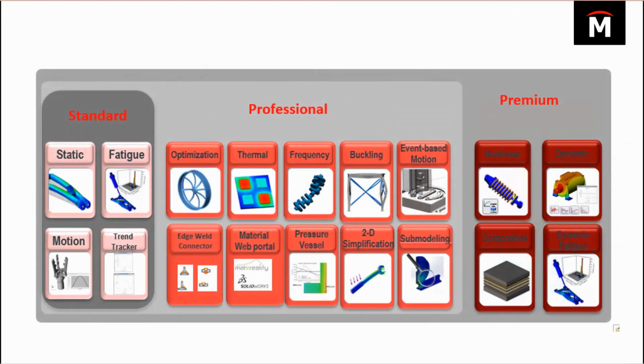I want to mention just quickly the 3 different packages of simulation. You might already know that if you buy just a CAD SOLIDWORKS Premium, that actually comes with a linear static solver, but there are sim licenses just on their own. There's a standard, professional, and premium. Today I just wanted to talk about nonlinearities and using that solver, but in addition to that, you can deal with composites in any of the linear static study types as well, composite modelings. Dynamics are here as well, linear and nonlinear dynamic, as well as dynamic fatigue. So all of that fits inside of the simulation premium model.